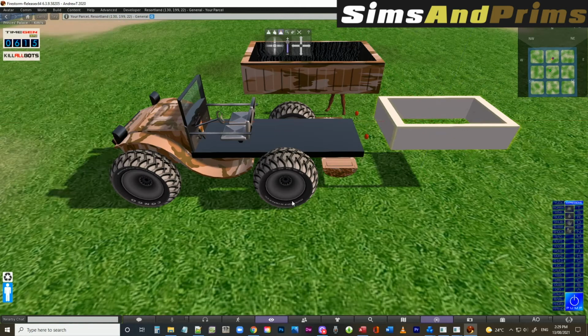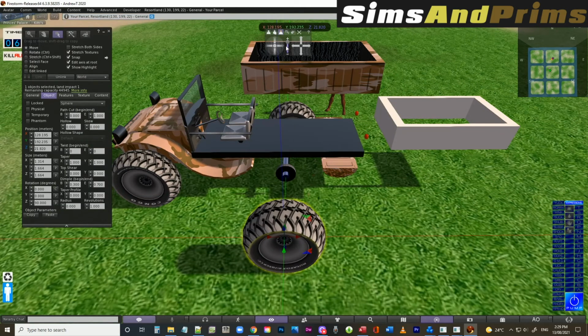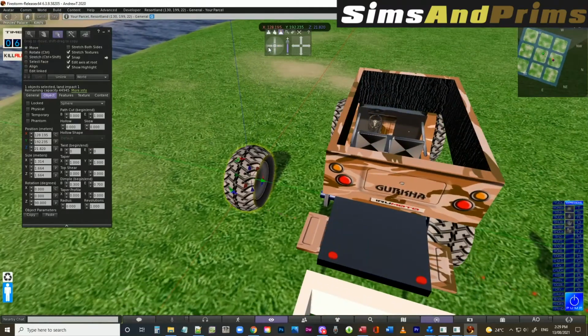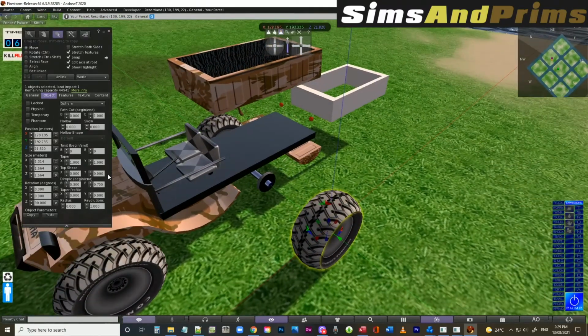Likewise, this, for argument's sake, is a sphere, believe it or not. It is a sphere with two dimples cut into the side of it. So you see here it says sphere. If you go down the bottom here, it says dimple, begin, end, 0.3 to 0.7. So if I want to try and replicate that, I'd go to the create tool there. I would choose a sphere. Okay. And let's get some specs off this thing. That's the size of it. We'll copy those sizes to save us entering it now. Paste.